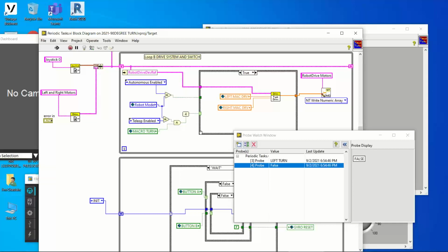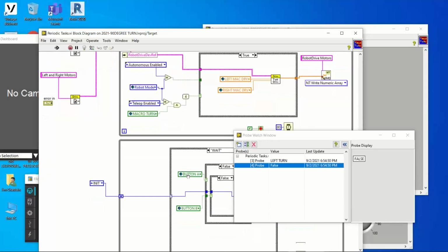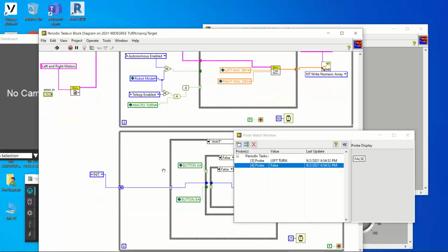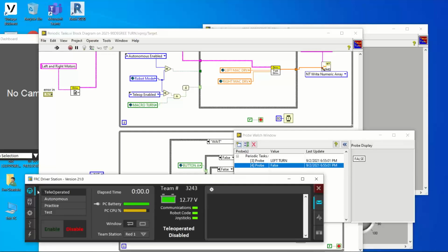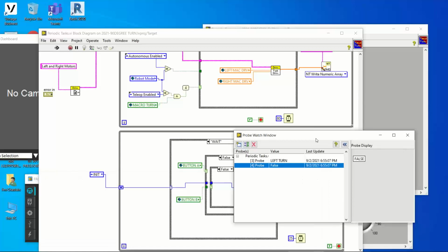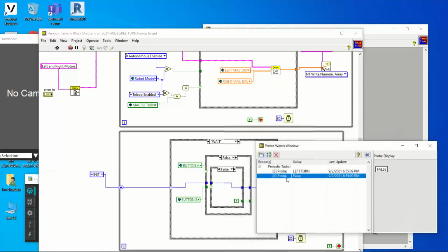only works... Now this is a gotcha for state machines and periodic tasks: if I'm relying on some signal to carry me through the cycle, that's an actuator, that's not going to be enabled until I enable my teleop. So that's something you need to be aware of. And I've been bit more than once by exactly this situation. So how do I reset it? I reset it by starting and stopping and vice versa.